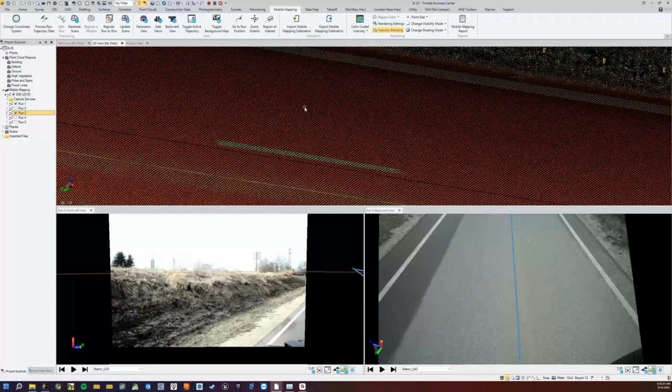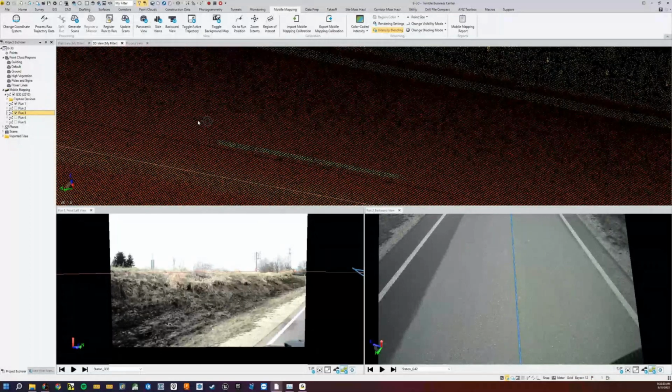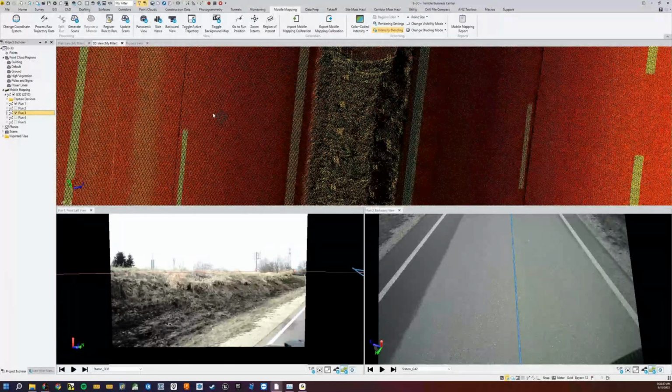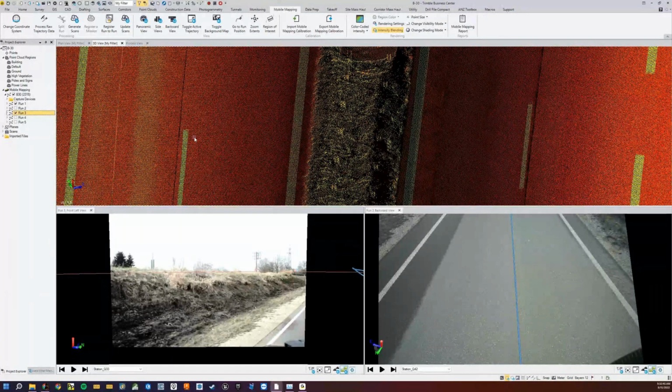In most cases, I think it's a little bit overkill for asset extraction or road surface modeling. You probably don't need to run it at this full density. But one of the cases that I do like it for is pothole and rutting and basically any kind of pavement condition inspection on a highway. That's generally one of the workflows that requires the most density to do well. Having that extra density, you might get away with one less pass, or with going the speed limit instead of slowing down a little bit. There are a couple scenarios where that extra density could be key.